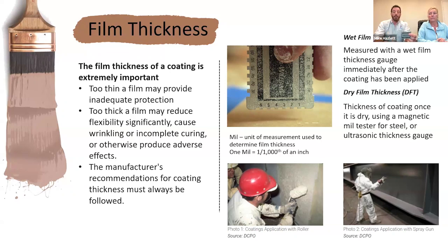They're different lengths. So when someone's spraying a wall or rolling out a wall with a roller, we'll walk up right after while it's wet, press it against the wall, take it off, and apply it to a piece of wood or cardboard, and the last notch that has a coating on it will give us our thickness. Very state of the art, it's very primitive, but with that, this really gets us a visual.